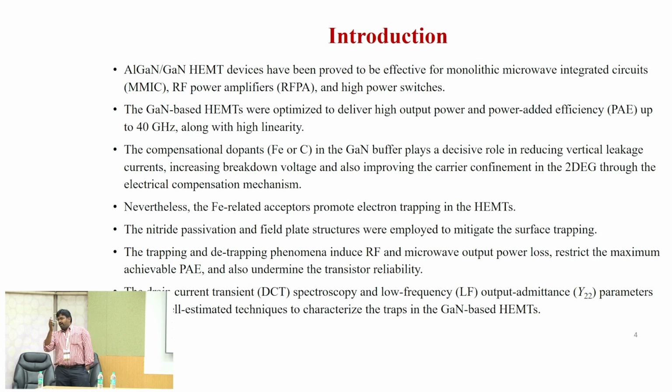The trap activation energy may be 0.6, for example, but you may get 0.4 or 0.5, because of self-heating effects or maybe Poole-Frenkel emission or field assisted emission. By incorporating these effects in the simplified Arrhenius relation, we can extract the exact zero field activation energy. Zero field activation energy means the activation energy when there is no field.